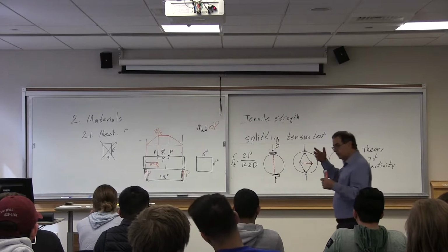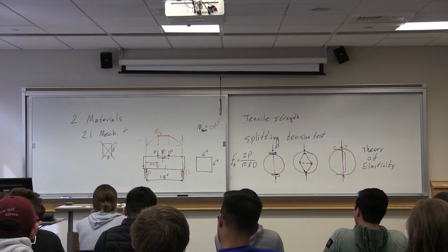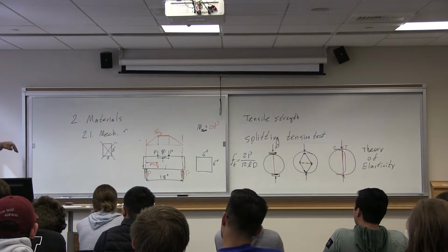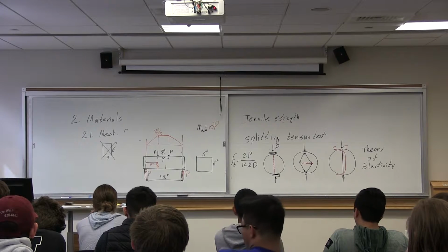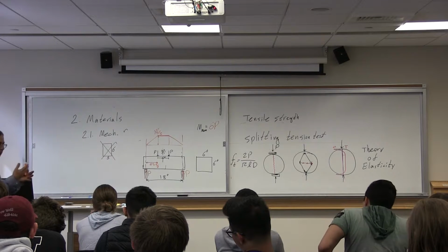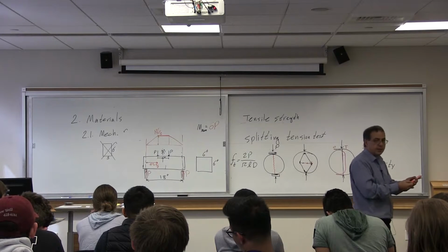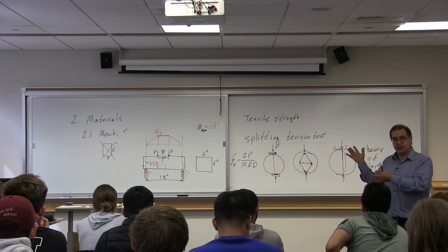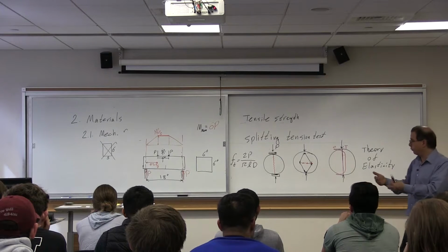We said when we design and we look at evaluation of a system, what we need is internal forces. That drawing shows the internal force applied to that beam. When we say force, we use that term rather loosely. We consider moment also as a force. In physics, if you write on your physics exam that moment is force, you may lose some points. But in this case, you can think about moment as a force because that's an internal force.